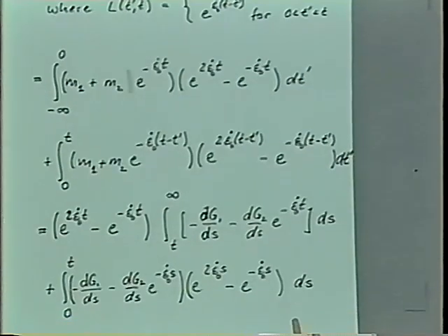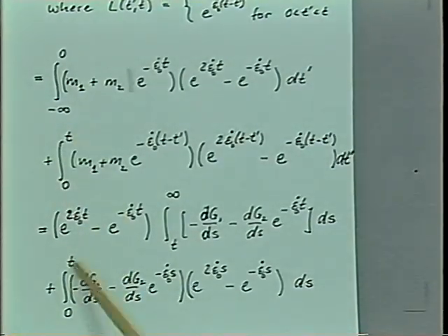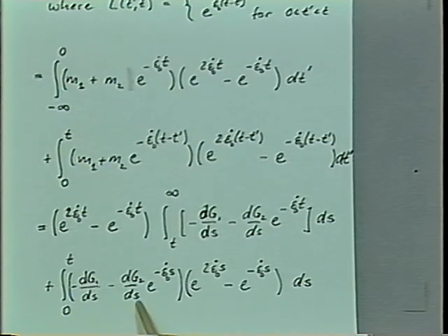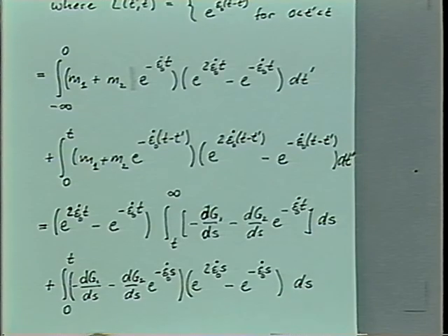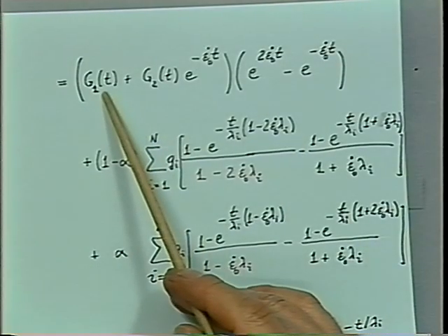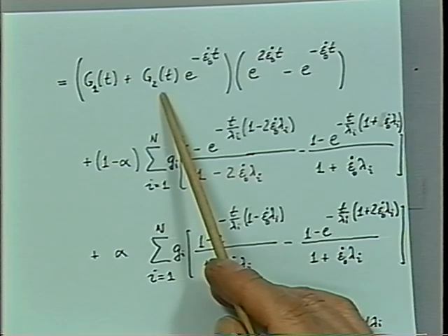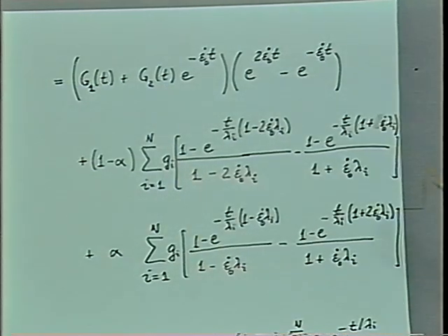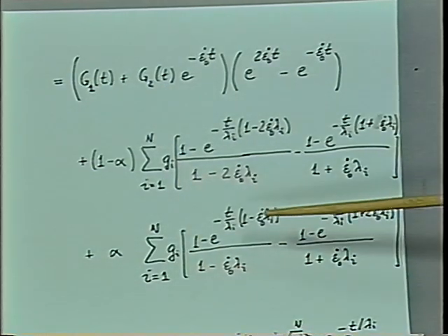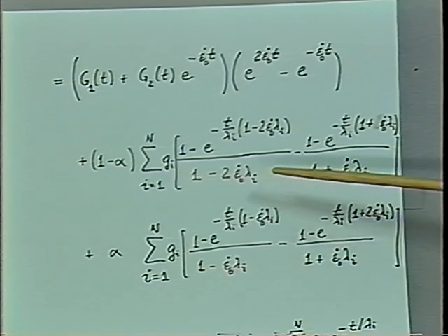And we can formulate now the second integral from 0 to t. And again, we replace the memory function with the derivative of the moduli, the Finger strain modulus and the Cauchy strain modulus. This integrates now further in the first part very easily. We don't have to specify. We just integrate. We had the time derivative of the first modulus and the second modulus. And when you integrate this, you get the moduli themselves. That's why we introduced that. But for the second part, the integral is too complicated, and we have to specify the relaxation behavior.